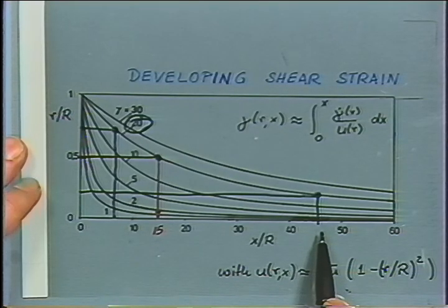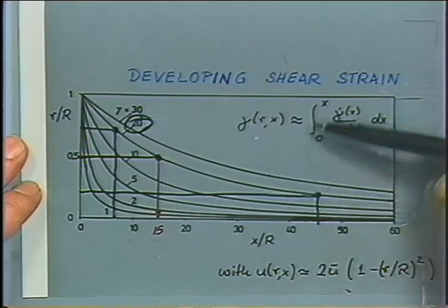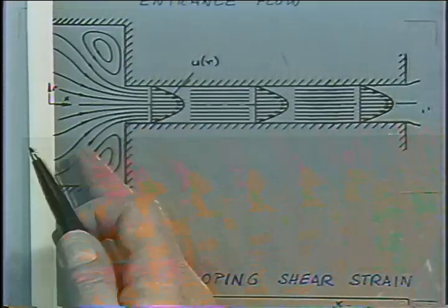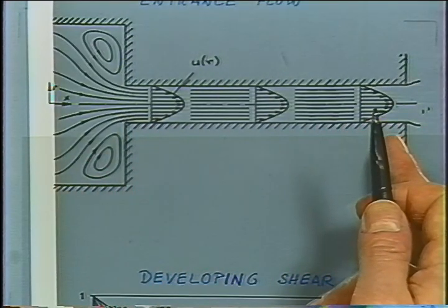In birefringence experiments, you would probe the sample over the whole cross-section, and you would see that in the center line, it needs a long, long time to introduce sufficient strain and to achieve steady shear flow conditions. Steady conditions would also be reached with time in the linear viscoelastic range, if the deformation or rate of deformation is very small. But that time is so much longer for most polymers than the residence time in the capillary. It will rush through the capillary before it can equilibrate.